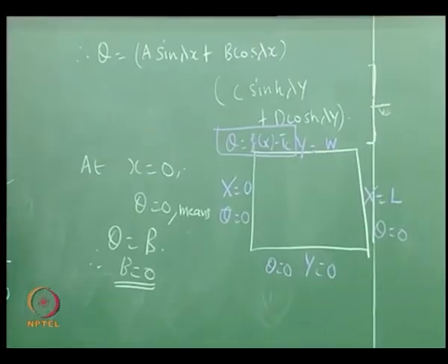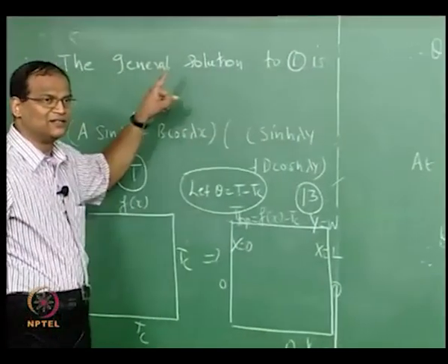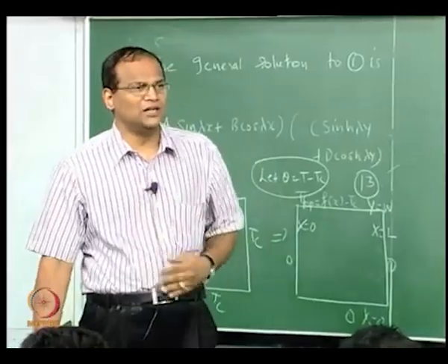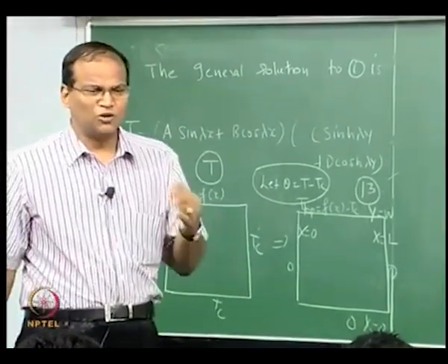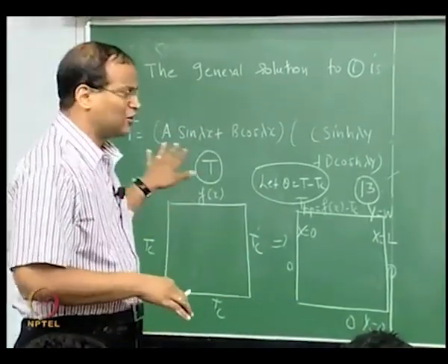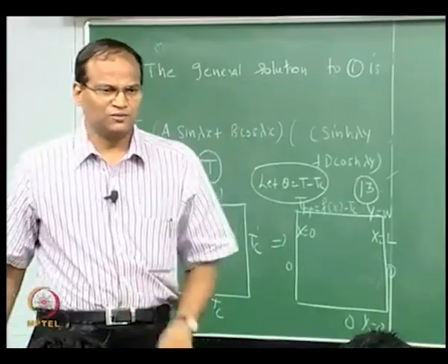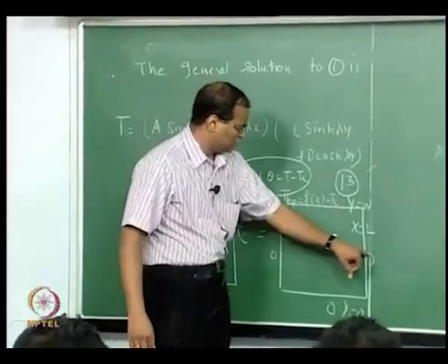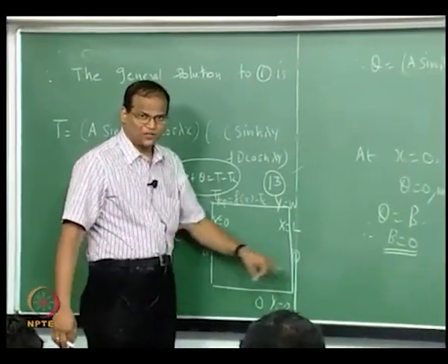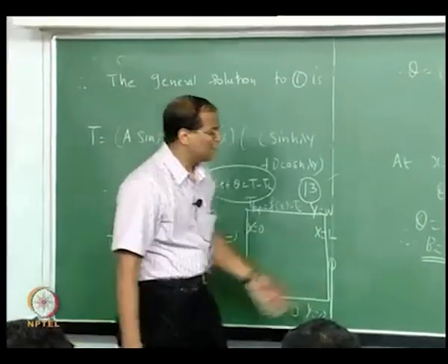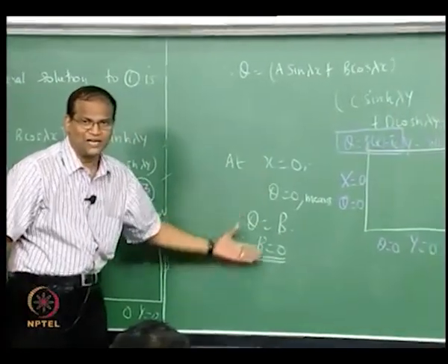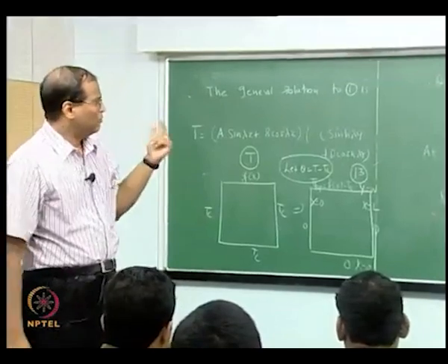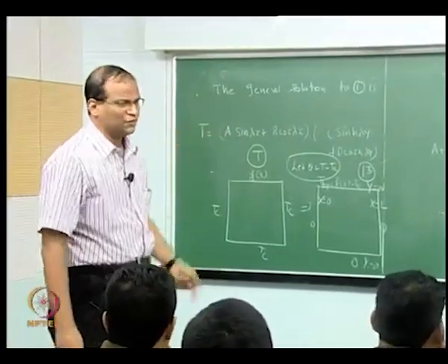It is not possible to solve this equation with all of these inhomogeneous boundaries. The method of separation of variables can handle only one inhomogeneity. That is why homogeneous means, very crudely, a first-kind or Dirichlet boundary condition that we make equal to 0. Therefore I am defining a new theta as T minus TC, so that it is 0 on three sides, and then I can do some magic like this, because I cannot invoke many of these things if it is not 0.